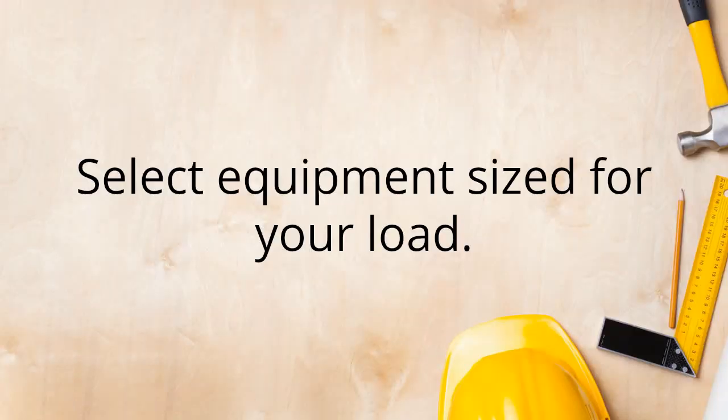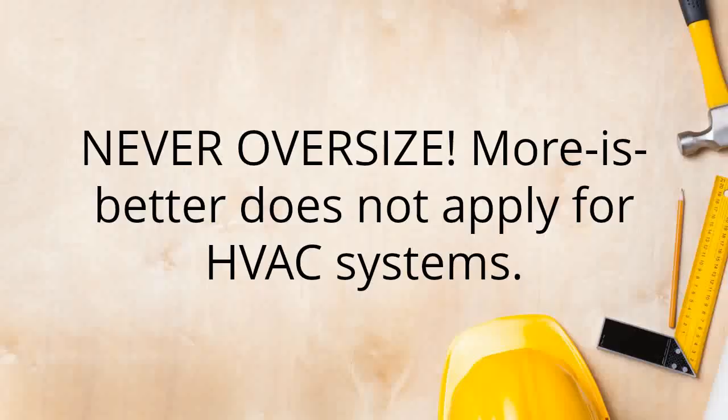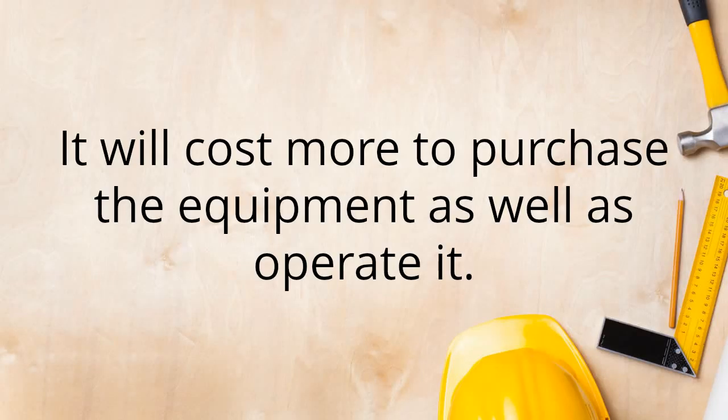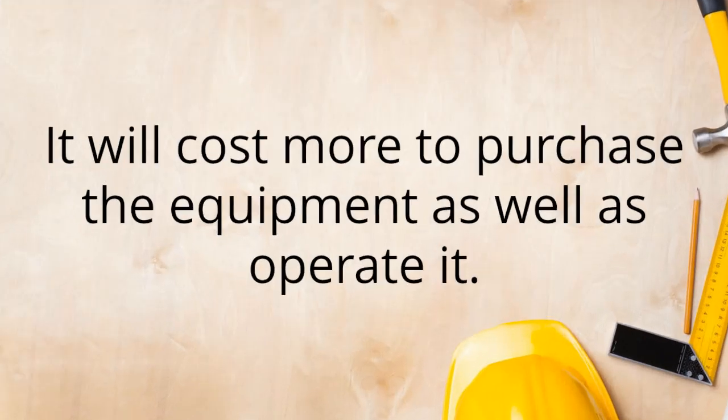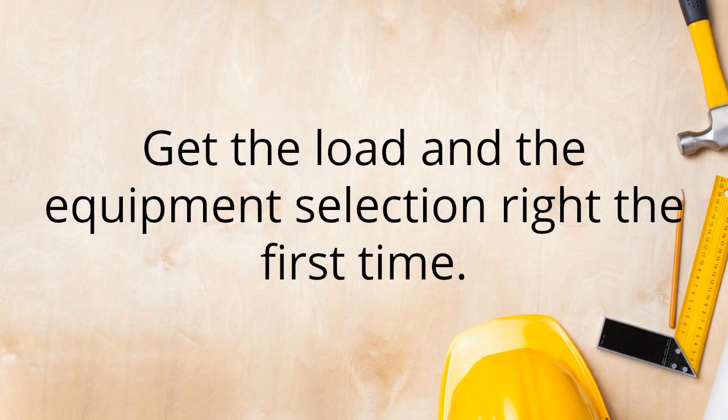Select equipment sized for your load. Never oversize. More is better does not apply for HVAC systems. It will cost more to purchase the equipment as well as operate it. Get the load and the equipment selection right the first time.